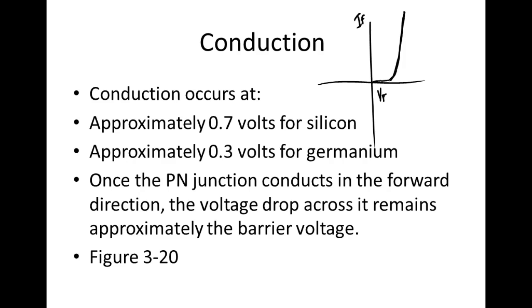Then you're going to set up this VI characteristic curve. We call it a VI characteristic curve. Y'all understand why? The vertical axis is the current, and the horizontal axis is the voltage that causes that current to flow. You'll see it does this little slope right here. You start going up, and you see when it starts conducting. If you put a potential across it, there's going to be a real small current flow, right?